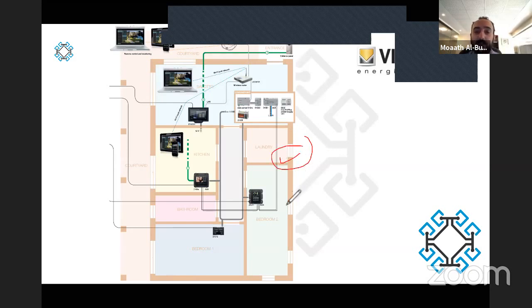Another important thing that you need to understand here is the power cable. Some of the screens that we have here require an additional power cable. For example, this screen and this screen require additional power. So our power supply will give you an additional port, and you have to run a power cable from our power supply to these screens. Is it clear? The power supply here will power the bus cable line, and at the same time it will have another output for the screens that you have to run a special cable for.